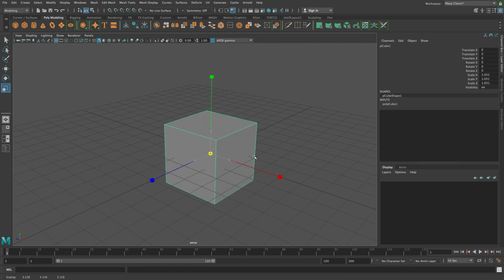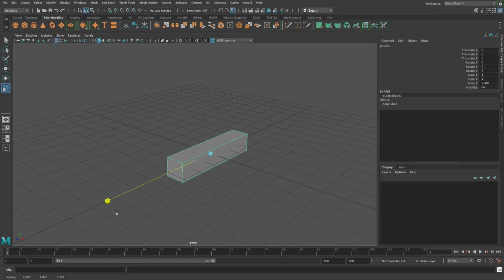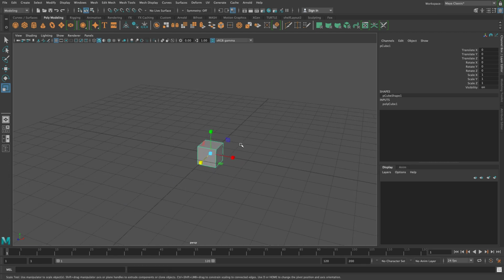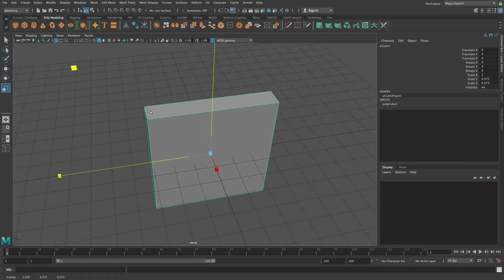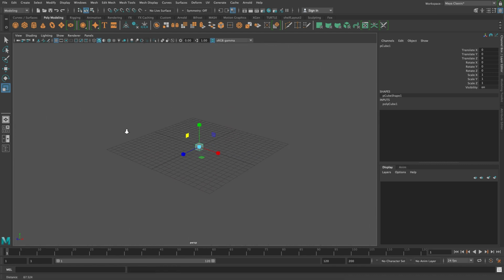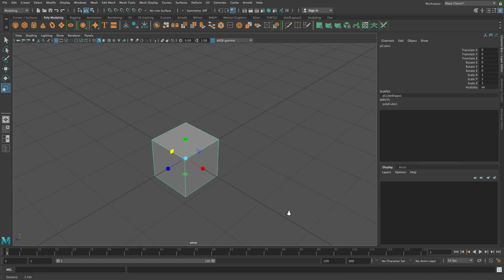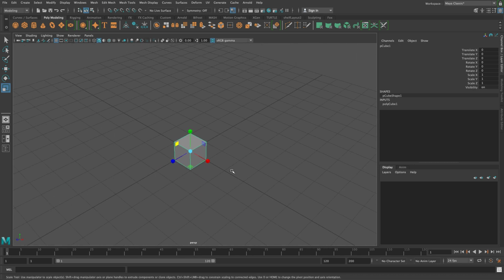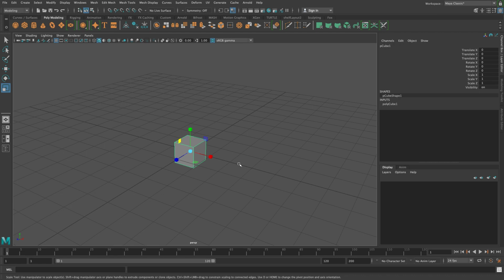You can scale in all directions, or you can scale in one direction at a time, or you can scale 2 different directions at the same time. Okay? You can play around with that and get used to utilizing that tool. And of course, if I don't want to scale, rotate, or move, I just want to select an object, that's my Q hotkey, which is my select key.